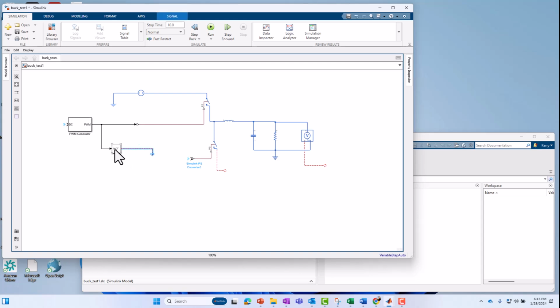So anyway, we want to drive the output on the low side with the inverted signal, the complementary signal that we're driving the high side with. And a simple inversion will do that, a NOT operator. Again, not a circuit NOT operator, just a behavioral NOT operation in Simulink. But this is a quote unquote logical signal. And over here, we're driving this kind of analog real world thing. So we can't drive logical and real. So we have to do what's called a data type conversion here.